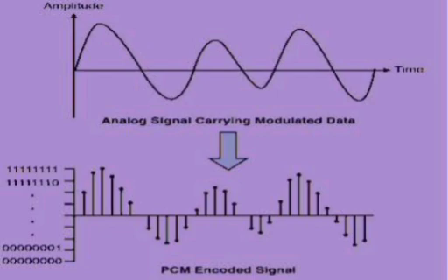Coherent FSK: S1 of t equals A cos 2 pi F1 t, S2 of t equals A cos 2 pi F2 t. Bandwidth equals 2 RB plus F1 minus F2. Probability of error is Q of root of A squared Tb by 2 N naught.